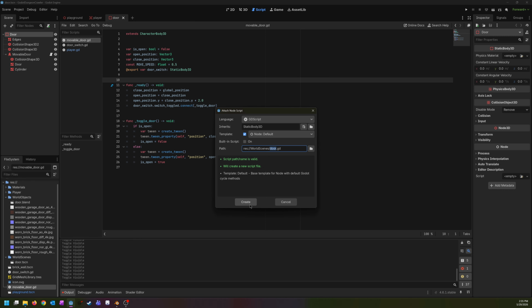And then we need to connect the signal. So in our scene here, the door, and now it's kind of out of position, you can see, so we just need to adjust that. But door switch, we can reconnect there, and then for the door, transform around the Y, we'll go 90, rotation 90, there, and then just minus 0.5.